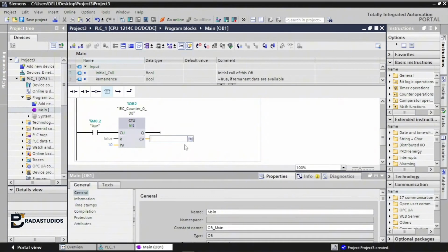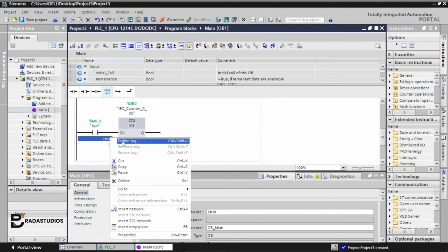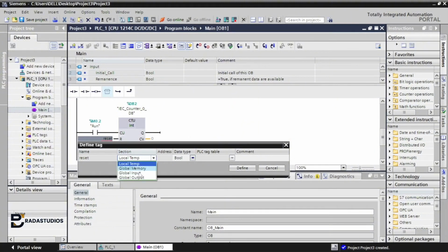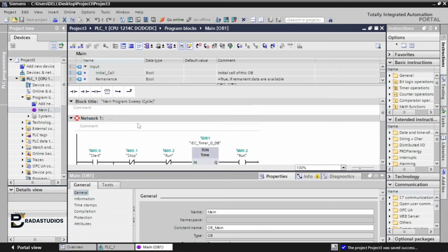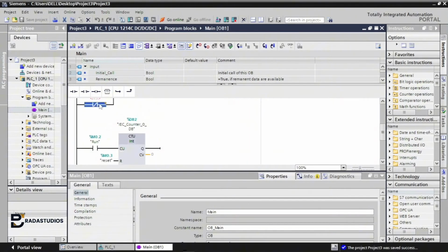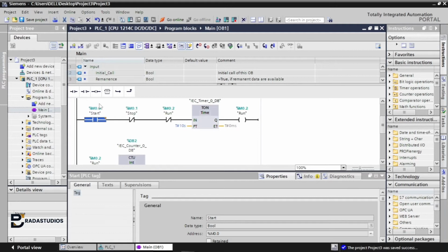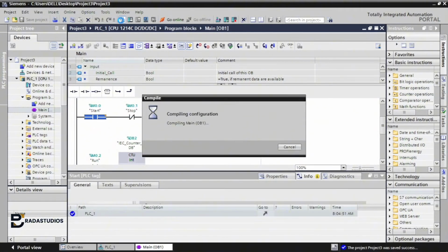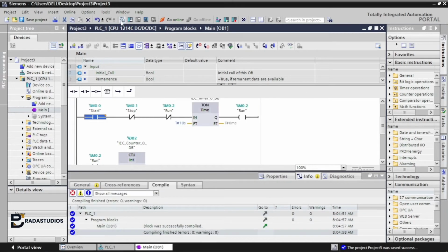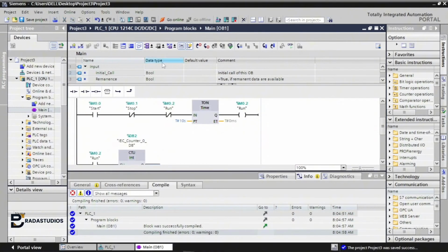So we'll now set our reset for the counter. We just name it reset, so that anytime you want to reset the counter, you can reset it. And then we'll set the preset value for the counter. We set it to maybe 10. Okay, and then we just give an output. Here I'll give an output and I'll just name it output.